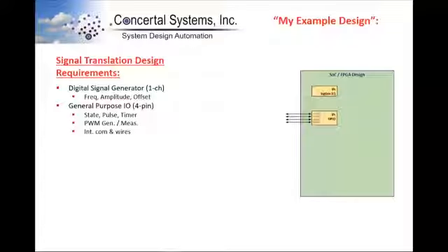It has 4 pins of GPIOs. The feature set of this IP not only allows the user to program the state, but can key off an event that allows it to generate a pulse, and it has integrated timers so it can generate pulses of specified durations, or it can measure pulses of input durations on the input pins. So it can be used as a PWM generator or measurement tool.